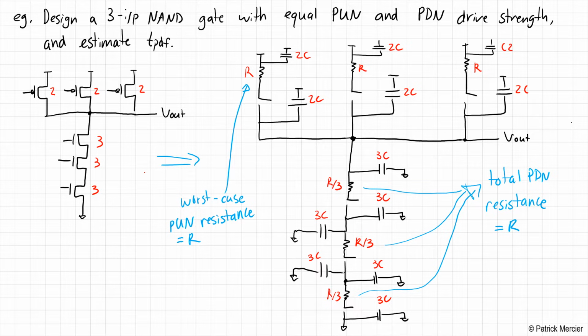Okay, so we are interested in analyzing the pull down propagation delay, or the propagation delay of the falling edge, which means we'll assume that the PMOS transistors, one or all of them, were all connected initially to VDD. And then at some instance in time, all of their switches open and all of the NMOS transistor switches close, therefore connecting the output to ground. And so what this means is that all of these capacitors at all of these internal nodes have to discharge from VDD to ground.